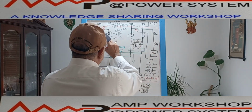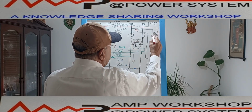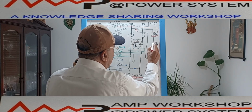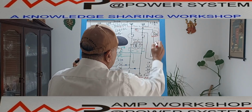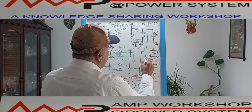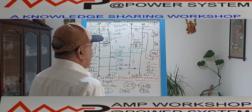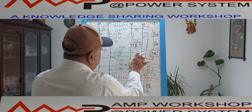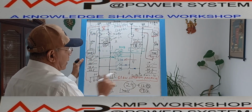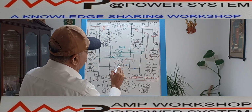At that time, as this relay dropped out, this 27A contact comes back to normal, that is 27A remains NC, and 27B is energized, means this NO becomes NC. So both are NC, and control supply comes to this KMA contactor, and KMA, the negative side going back, so it is getting energized. The moment it is energized, now what do we need? As this is healthy, we need the power supply to come from here to here, because there is no power supply over here. The moment KMA is energized, you see here, we have used the KMA NO contact over here.